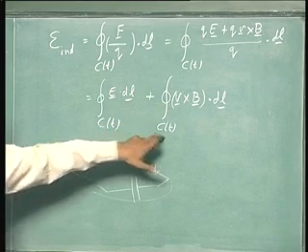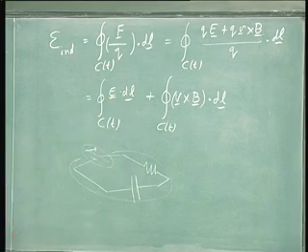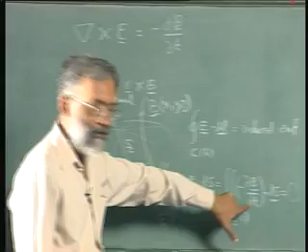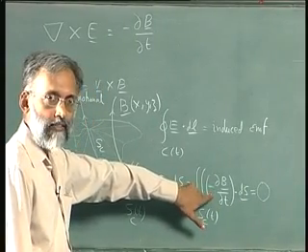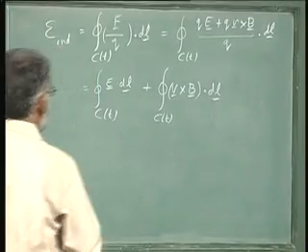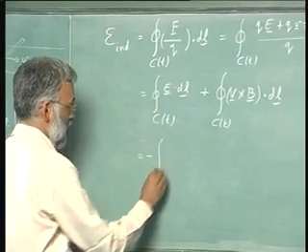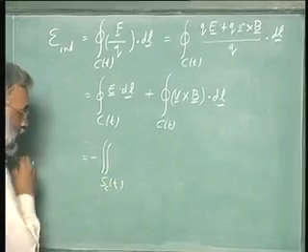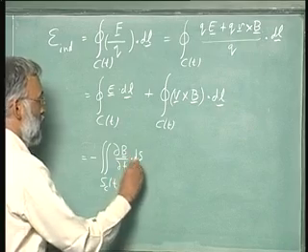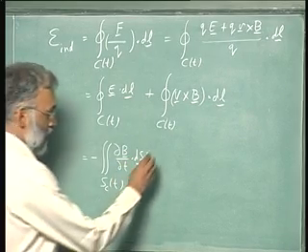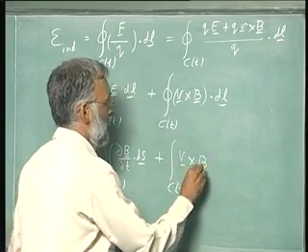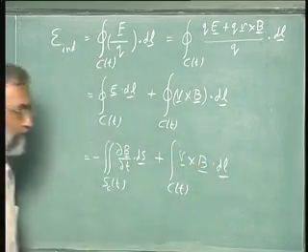So I have two terms left, and one of these terms is exactly what I have used Faraday's law for. And that term gives me the transformer part, minus del B del T. So I can write that out. So this term is equal to minus surface integral, which is changing in time, del B del T dot ds from Faraday's law plus a term C of t V cross B dot dl.